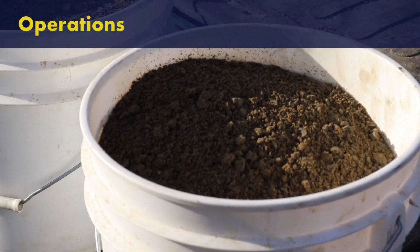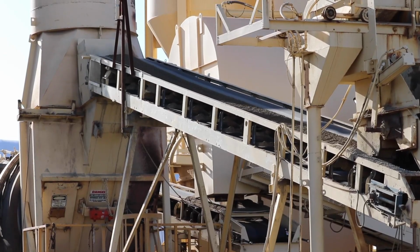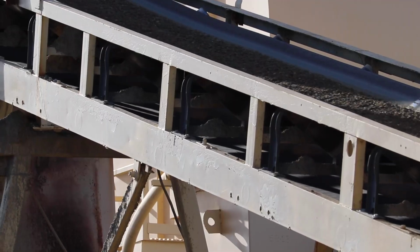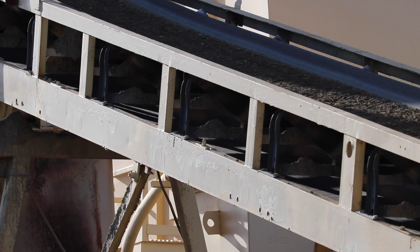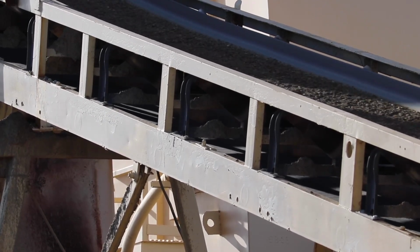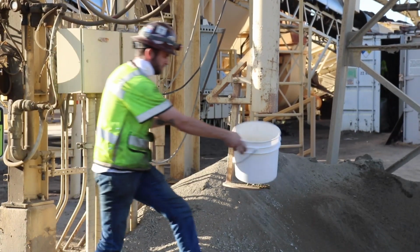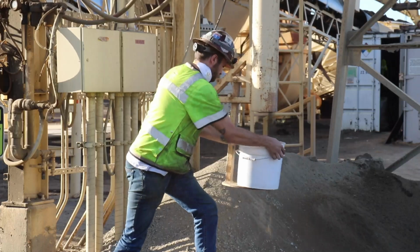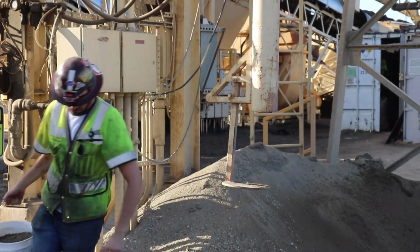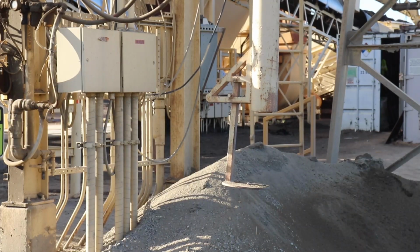Operations are split into two components: aggregate production and binder production. Aggregate production follows the normal manufacturing process for conventional hot mix asphalt. This is comprised of the quarried aggregate being processed into the specified gradations as identified by the mix design. Additional equipment is required on-site to produce the RAC asphalt rubber binder product. The binder production process begins with the delivery of asphalt binder. The standard grades required by Caltrans for RAC are PG64-16 and PG58-22, although other grades may be used depending on the prevailing climate.